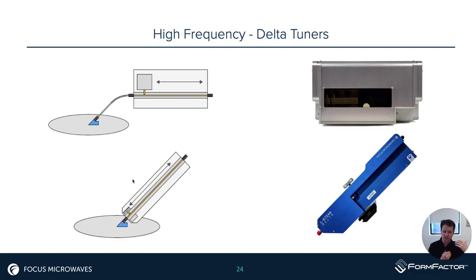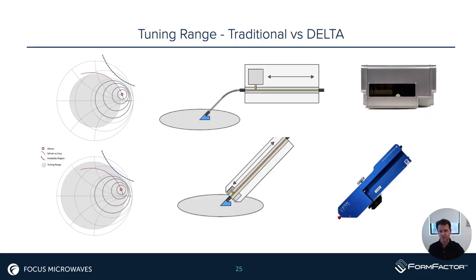And if the tuning range is too high and you are hitting those instability ranges, well, you could bring it down. It's always easier to bring the tuning range down than to bring it back up. That's something you can't do in noise. So here's just a quick example. You see that this is a poor tuning range, and this is a better tuning range. Probably slightly exaggerated, but it's just to show the example.